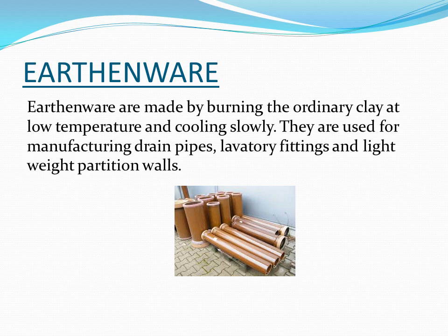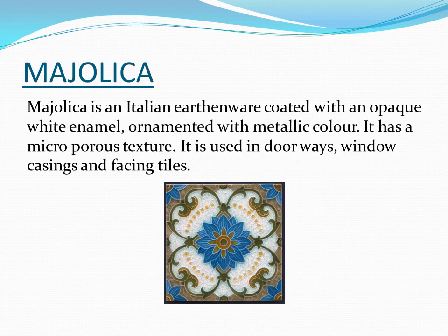Next comes Mesolithic, potter's clay. Potter's clays are finely dispersed secondary earths largely consisting of clay minerals such as kaolinite and hydromica with more or less quartz, feldspar, iron oxides and carbonates. What is redeposited? First, you know how clay is deposited on the seashores, under the beds. It is deposited and then again redeposited. Potter's clay is used to manufacture face bricks and tiles.